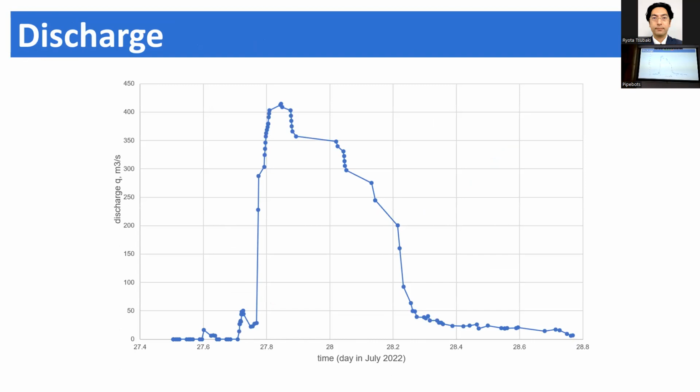Actually, the surface velocities we need to measure in the orthorectified image. For that, we need the water level. So we orthorectified at the latest highest water level that we measured, and we kept it there. So already there is an error because we didn't correct the orthorectification for different levels. Next one.